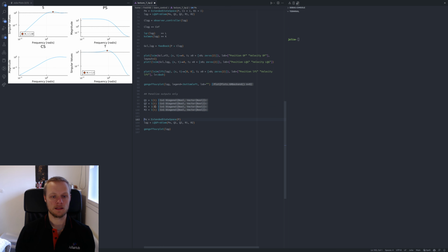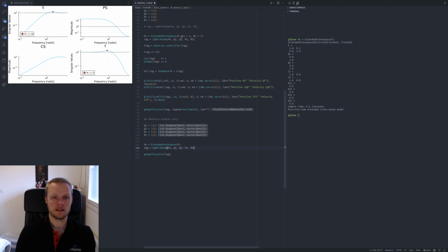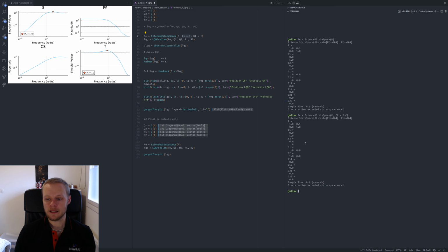So that corresponds to we have a single source of state noise acting on the system. And then when I create the state space system, I do not provide this C1 equal 1. Then C1 will default to the C matrix in this system P. So I could equally well have created the system like this, C1 is P.C. That will give me the same result. So that now indicates that my controlled outputs are the same as the measured outputs.